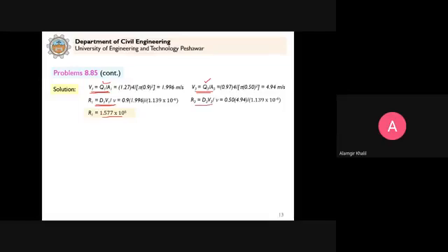And we calculate R3, and it comes out to be 2.17 into 10 power 6. So from our values, both flows are turbulent. And we assumed while calculating Q1 and Q3 that the flows are turbulent. So it means that the assumption of turbulent flows is correct.